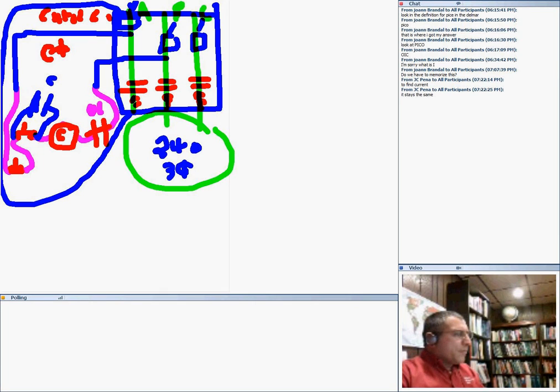What is phase 3 used for? Phase 3 you have to use to power the motor, right? You need 3 phases. We're only stealing 2 phases just to form a control circuit. The control circuit doesn't need 3 phases. It needs 2 phases. But the third phase is needed to power the equipment. Remember what I drew, guys. The blue stuff is just the control circuit. The power still needs the third phase.